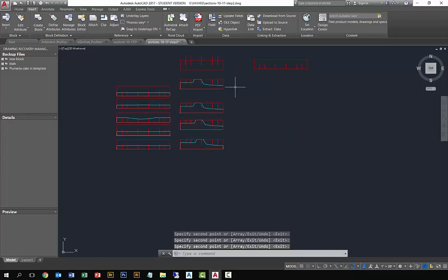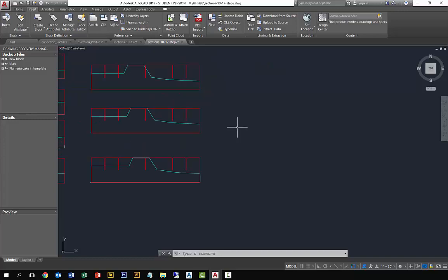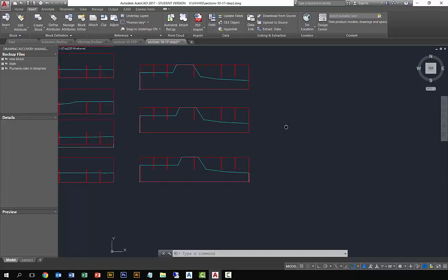the fact that for the longitudinal, you see the template for the jig will actually cut through both sides of the material. So you're going to have to shorten that, right? And then on the short section, they don't pass through the material. So you're going to have to lengthen those. And the rule is at least 50% of the material. If you go any smaller than 50%, you're going to have some failure or potential bending.